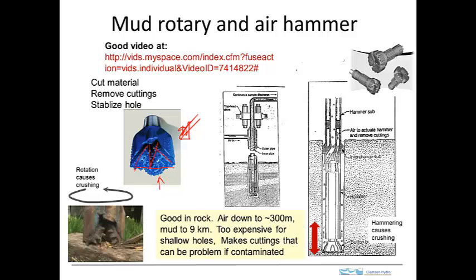And the important thing is that you see these little buttons right here, these little protrusions. Those are either hardened steel or carbide, and as the bit rotates, these cones rotate, and these buttons progressively push down onto the bottom of the hole. You can see that over here, I think.